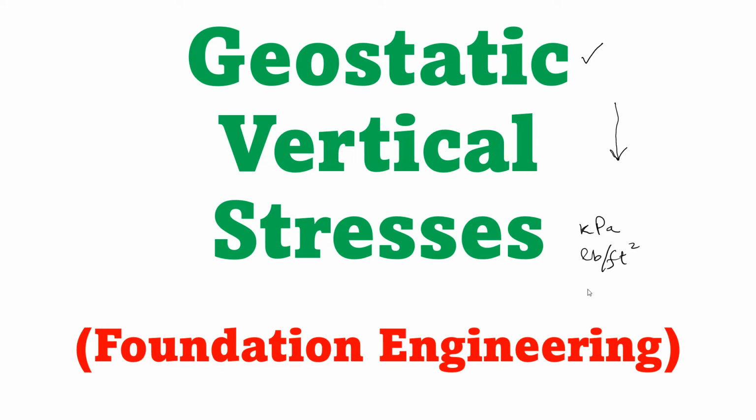geostatic vertical stresses. So first of all, we have to know what the vertical stress is. In most of the literature books, this vertical stress is denoted by sigma V naught. This is sigma V naught, which means vertical static stress. This O means static, meaning there is zero dynamic load. So it means the stress which is vertical, but the loads are static and nothing is moving.